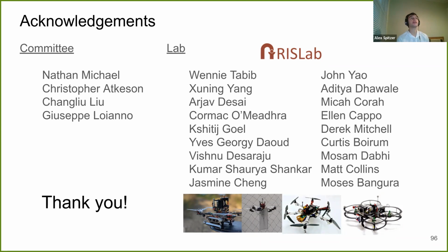But of course, the advantage of ILC is that you get a more certain guarantee that you will reduce the error, because you're directly optimizing for the error. ILC looks at the error and says, what do I need to do to lower that error? And it computes that correction. But forward model learning, which is what I'm doing, indirectly minimizes the error by minimizing prediction error. There's an interesting theorem: if my control is implemented correctly, then minimizing prediction error is the same as minimizing tracking error. But in practice, there are certain cases where that doesn't end up happening.